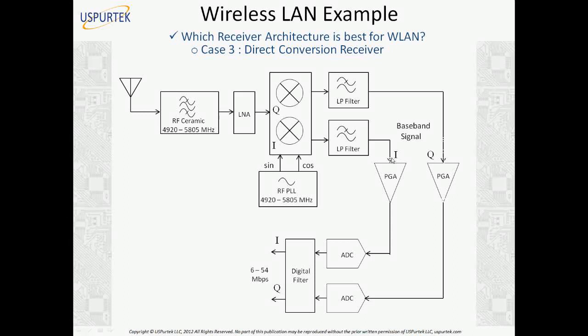How do we do that? One option is that we use not the same frequency but twice the local oscillator frequency required, to avoid coupling, so that it doesn't couple with the antenna. We use twice or half or maybe 3 times or 4 times the local oscillator frequency, so that it doesn't couple with the antenna.